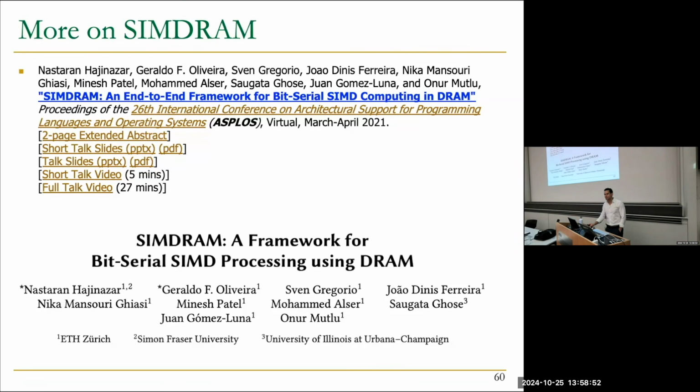And also, is there a limit to the size of the program we can execute, because the subarray has a limited size? Yes. And is there support for using multiple subarrays, moving data between subarrays? Not in this work here. For all of those operations, the data fits or can be partitioned in a way that you don't need to move the data across the different DRAM subarrays. But we discussed in the lecture this LISA paper, which connects the subarrays using some isolation transistors. And we can move the data using that approach, for example, if you need to move data from one subarray to another one because it may not fit.